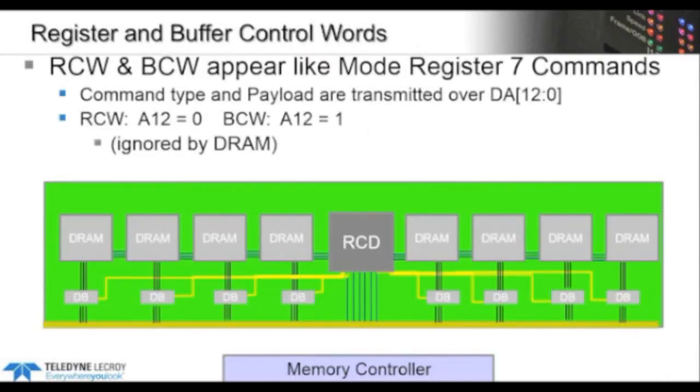Okay, if you're going to be involved with testing and qualifying LRDIMMs, it's really helpful to understand the structure and flow of these commands. This is some of the stuff that Doug talked about, but it bears repeating. Again, standard commands, your write, your refresh, your MRS, they're going to flow through the register to the DRAM.